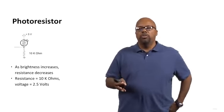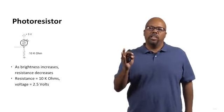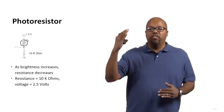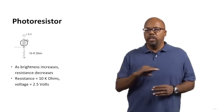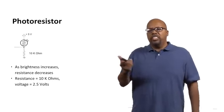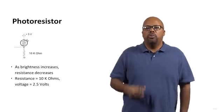So if it's 10 kilo ohms, then if we look at our voltage divider, we've got a 10 kilo ohm resistor on the top and a 10 kilo ohm resistor on the bottom, which means that the voltage will be divided in half. Since you've got 5 volts going from top to bottom, 5 volts in the top, 0 on the bottom, that middle point that we're measuring will be 2.5 volts because the resistors are even. So if the photoresistor has 10 kilo ohms resistance, then you'll get 2.5 volts.